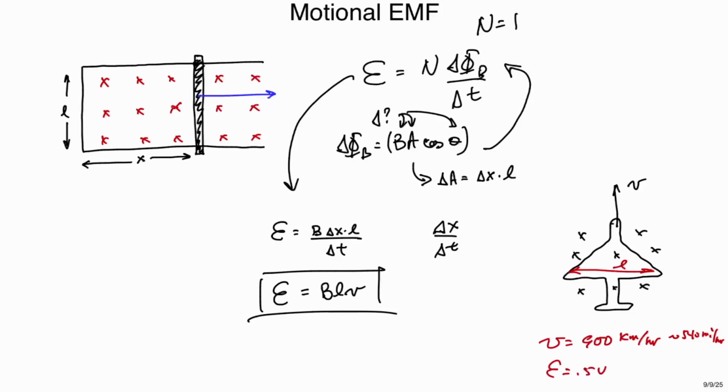It's pretty small, right? The Earth's magnetic field is pretty weak, so you need strong magnetic fields in order to have any sort of major contribution to this. As soon as the plane touches down and stops moving, the voltage goes away, so there's no danger. They don't even really need to design around this feature because of the shielding effect that the aluminum frame of the airplane has for the electronics inside. I wanted to give that calculation to show you that you really need either a lot of field or a lot of current in order for this to be a thing.